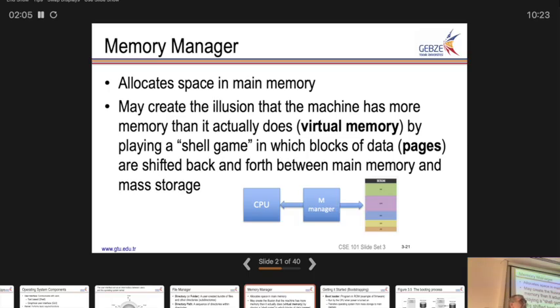Like get the number from 6E, and get the number from 6D and write the sum to 6F. Or go to program counter, some other address. So the program counter is reloaded with a certain beginning address so that you will make a loop. Are we together on that?